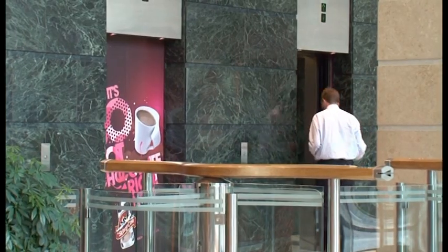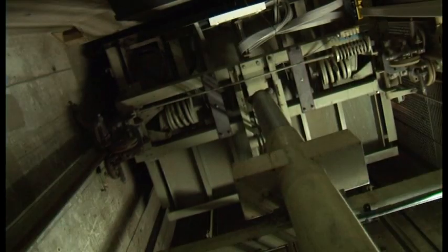It's important to say that the schedule does say mutual, so the electrical system should not interfere with the operation of other systems, for example, communication systems. A classic example is making sure that no electrical cables are run in a lift shaft, unless they're part of the lift installation.